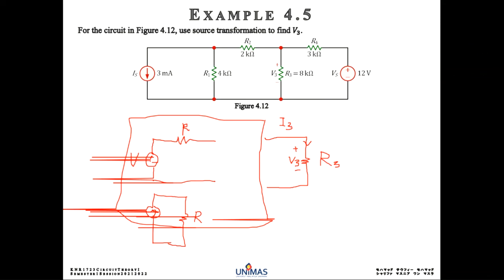In this case, I3 is equal to V divided by R plus R3. Whatever the value of R3, just change it and you can easily get I3. Same for V3, using the voltage divider, V3 is equal to R3 divided by R plus R3 multiplied by your V.